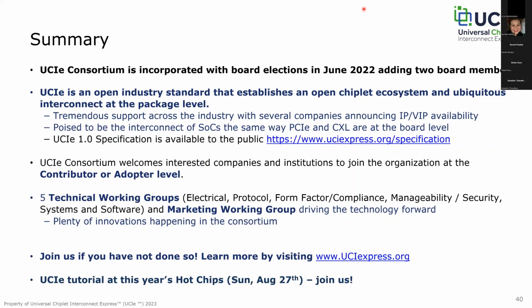In the future, as bump pitches continue reducing, there could be future generation versions of the specification that go even below 25 micron bump pitch support. I'm fairly confident that will happen. We can also look into the possibility of stacking the modules, similar to the stacked x32 module for standard.